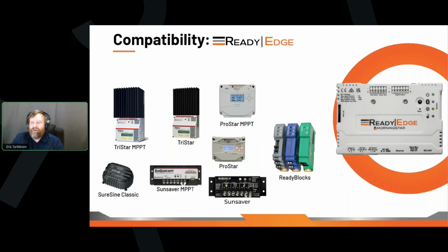So what do I mean when I say we can connect to products? In the last picture, I showed you the ProStar MPPT connected to the meter bus port. Well, the ReadyEdge can connect up to 16 of our devices simultaneously, 2 of them very easily through the meter bus port. So that's all of our products, including the SunSaver PWM controller, which does not have meter bus.